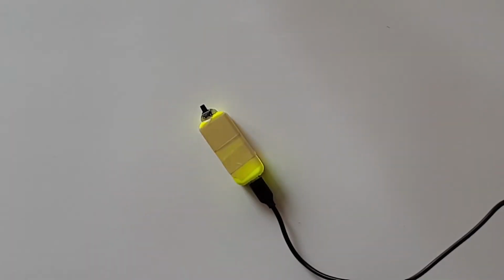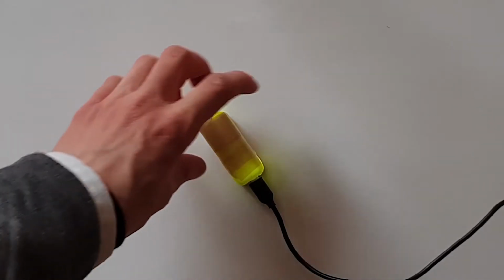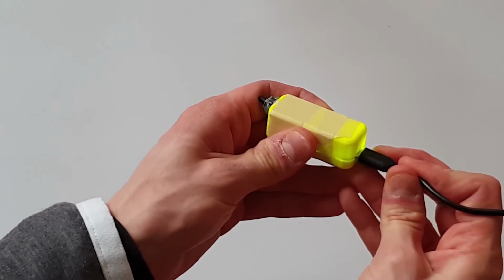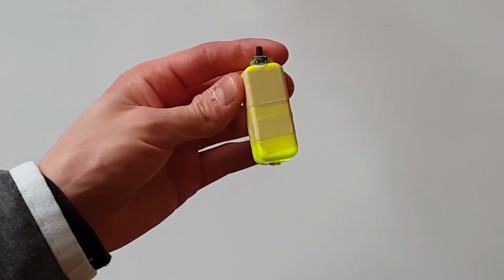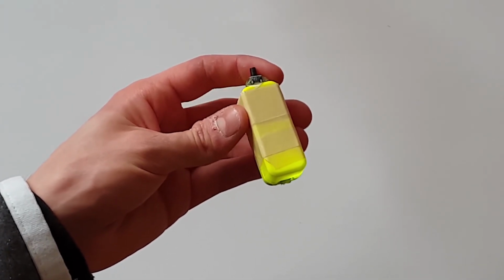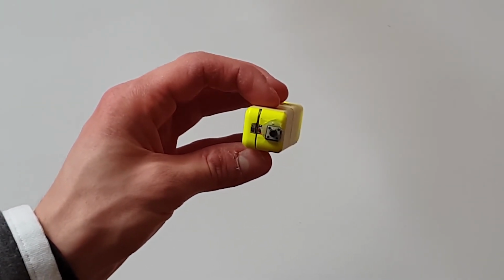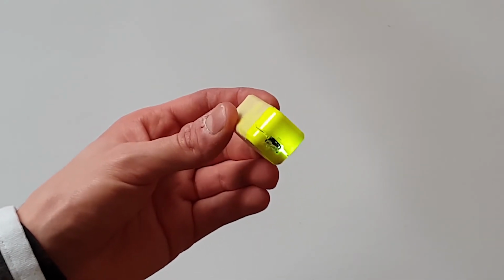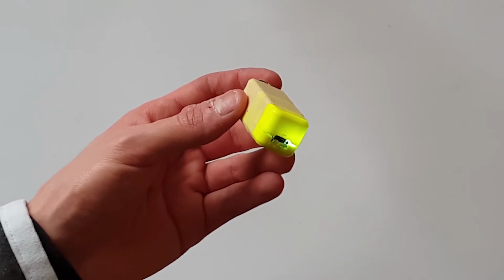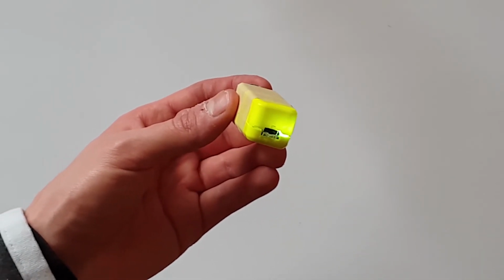Once we've uploaded our code to the Tactigon board, we can verify its functionality. You may now unplug the USB cable that we use to power and upload our sketch. As you can see, we have mounted a button that is connected to the GPIO 4 pin, the one that will read the state in our code.